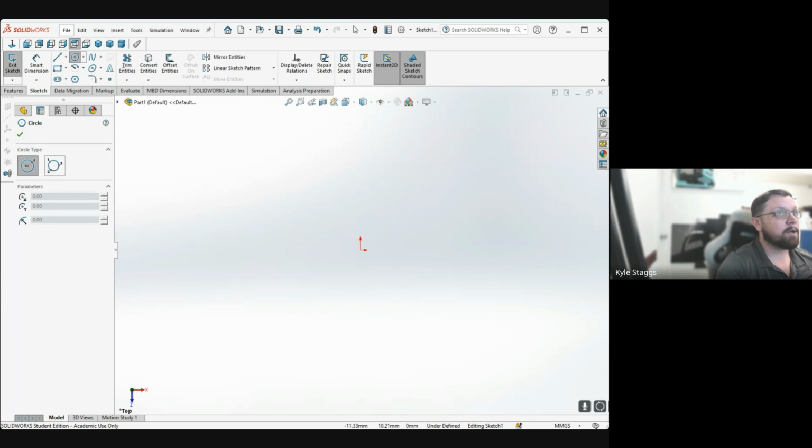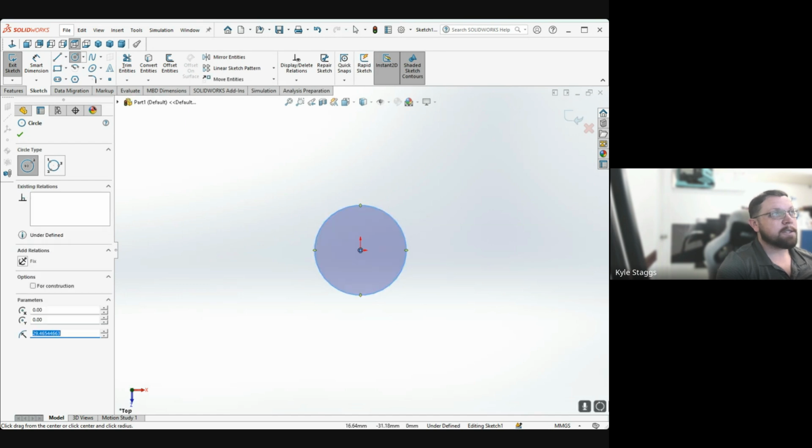Instead of drawing it like you would on a piece of paper, you're going to click and it'll show you a representation of the circle types. You can do a 3-point, or you can do a center point, and it gives you a graphic here that will help make it a little bit more visible. So you start with a center point, and then you give it a second point, which is trying to define the radius.